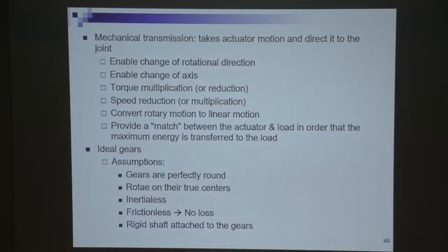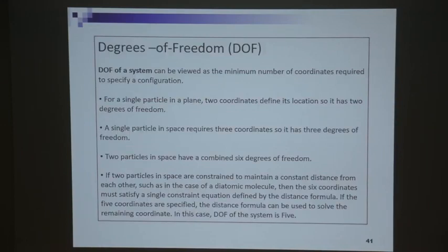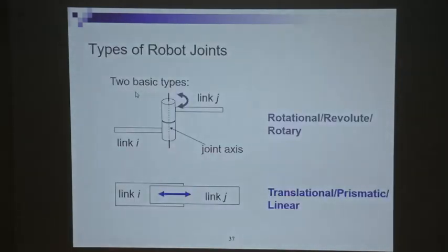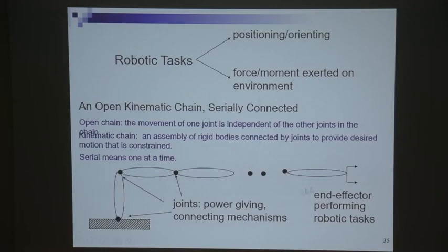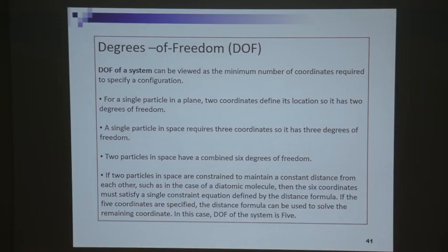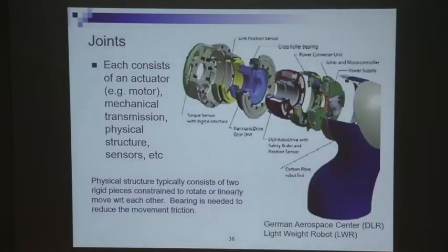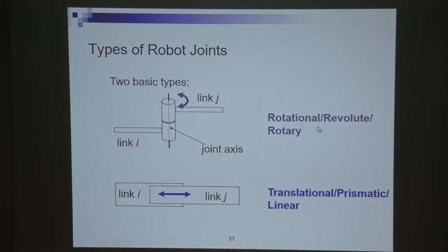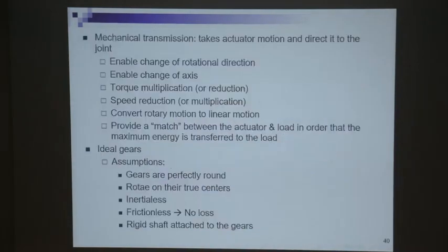When you talk about the joint, a related question is how joints link up together in a serial mechanism in this manner. Then the next question is the degree of freedom. There are two basic types, a rotational or revolute joint and a translation joint, and each of them only has 1 degree of freedom. A rotation joint can only rotate on one single plane, and a translation joint will only move along one single line. So this is 1 dimension.